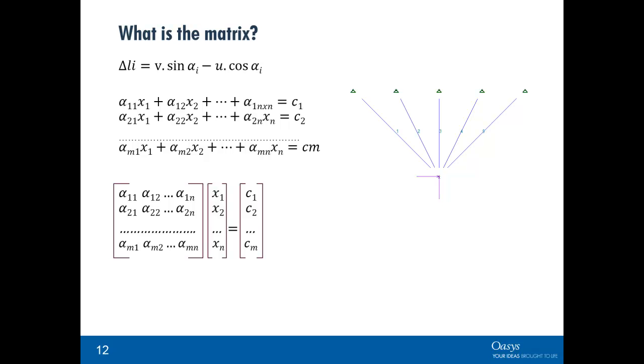So a bar will contribute only 3 lines into the matrix, whereas a beam 6. So it's worthwhile honing the elements down for an efficient analysis. Also crucial to note is that as everything's derived from the nodal points, elements must share nodes to be connected. Point is occasionally forgotten.